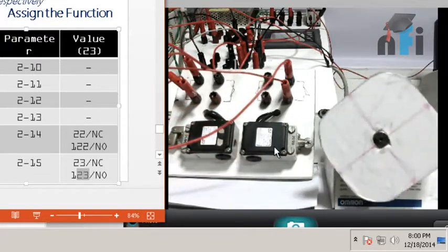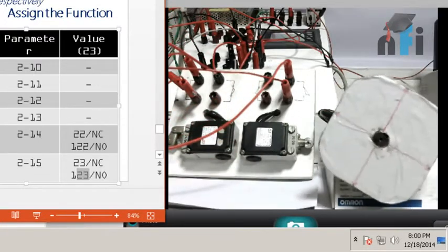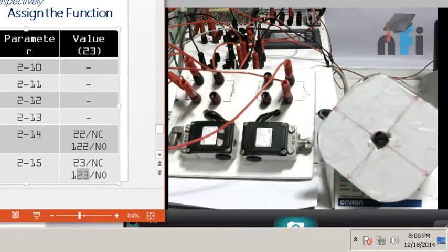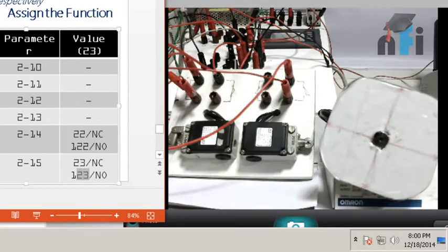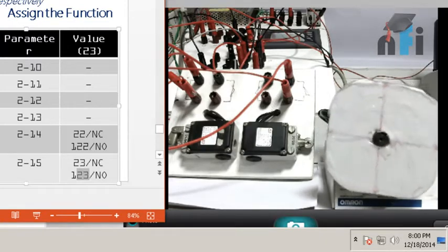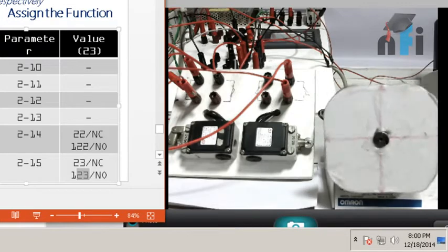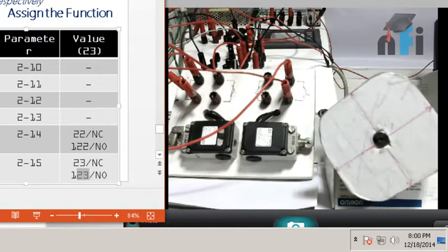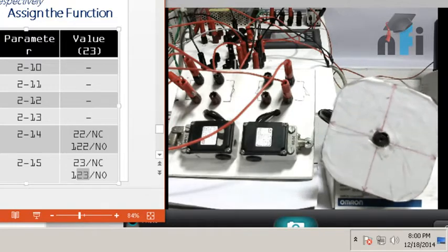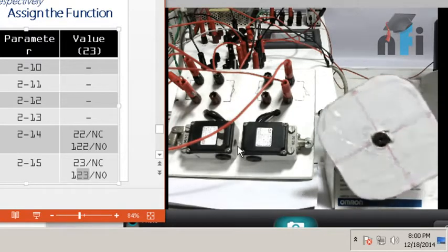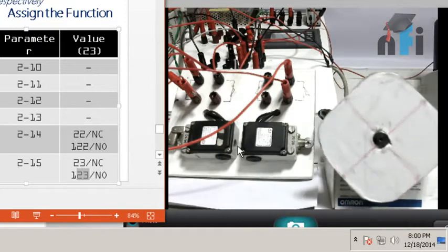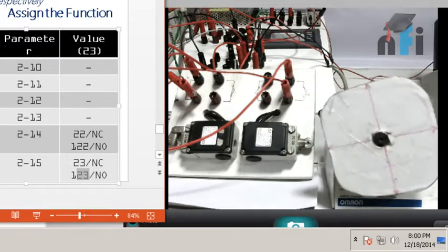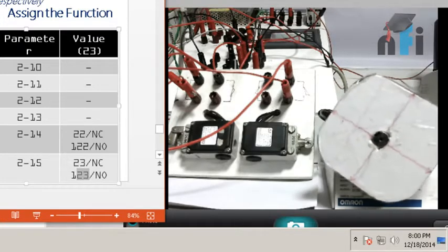These two limit switches can be installed at two extreme limits of your conveyor or your robotic arm or linear actuation. Just in case your bed or your slides reach these extreme limits, the servo should stop. So these are the emergency stop kind of switches. You can say that these limit switches limit the position of your slide, of your drive, to reach these two extreme positions, which can be any. You can set this position by changing the location of your limit switch.